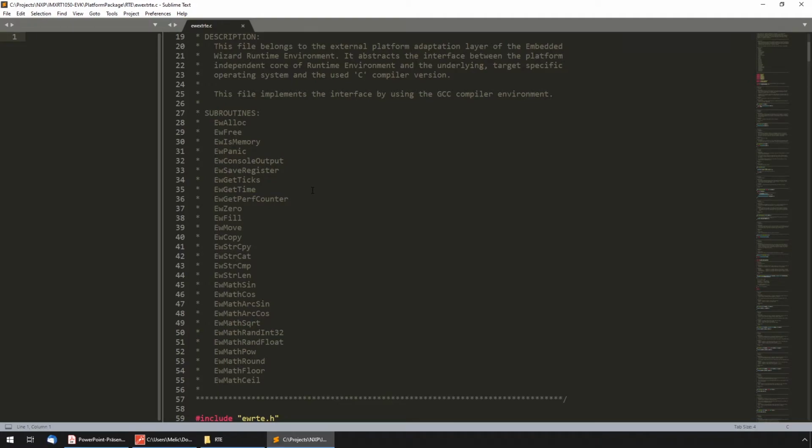And usually, as these environments are tested for a dedicated environment, in that case the NXP RT1050, please do not make any modifications there, because it's tested and it's there. But we have customers, and this is something that we have negotiated with the customer, that there is the possibility to adapt. Just think about you have a dedicated operating system and you want to ensure that all memory allocation is routed through your operating system code, rather than using our memory manager, for example. And this can be adapted accordingly inside this environment.